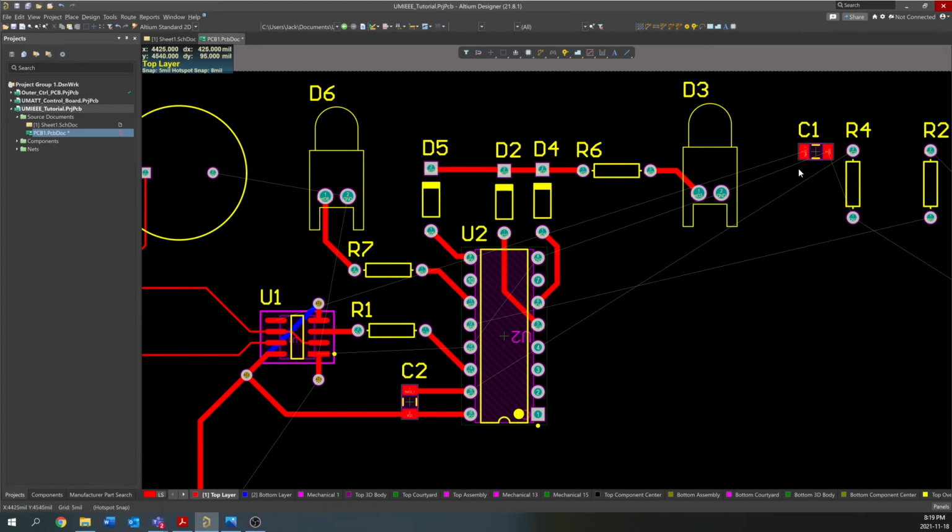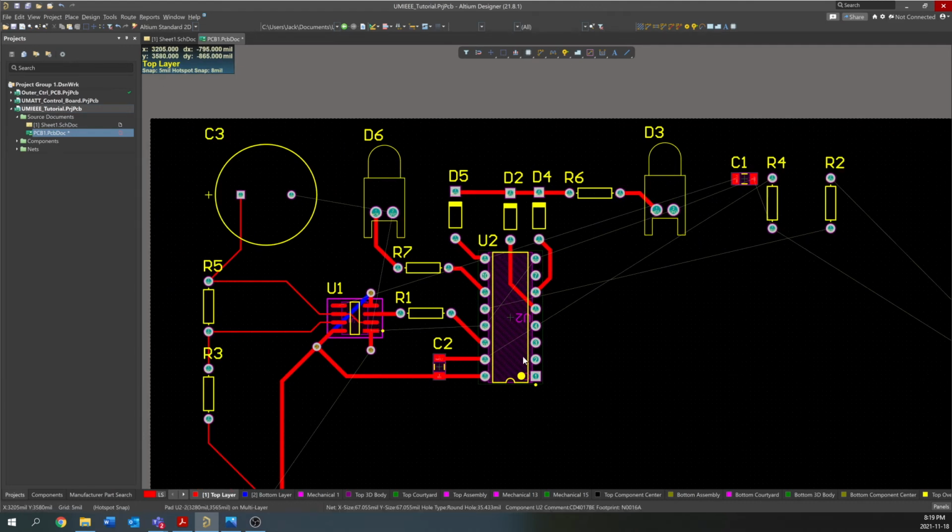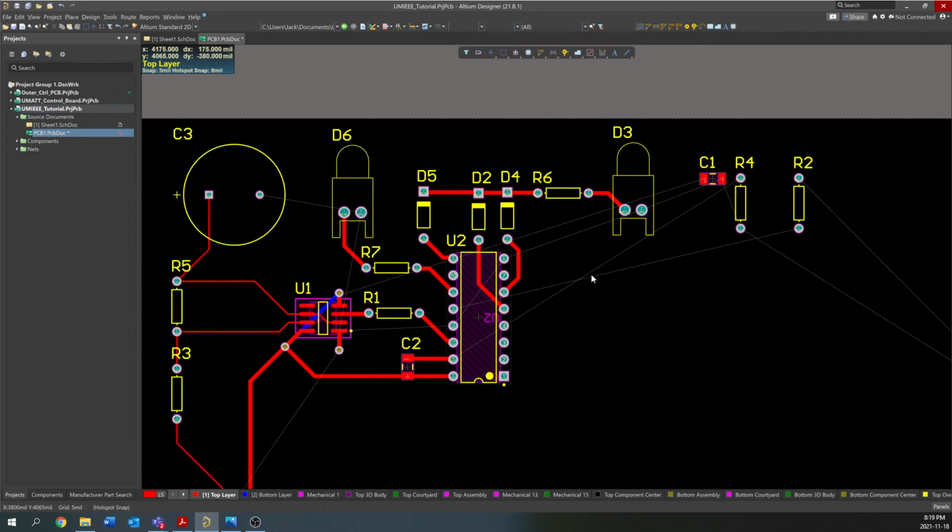So that's just my opinion for doing a different board with other ICs. Try to rotate the ICs and arrange your components so you have fewer rat's nest wires crossed over. That's the best thing to do.